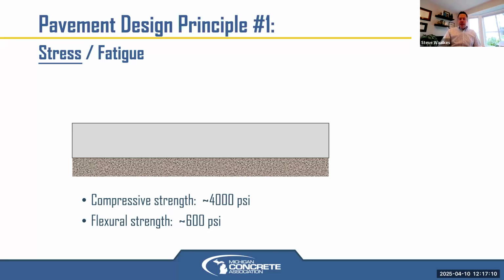As most engineers understand, we design things to reduce the stress on that member, on that material, whatever it is. And so that's one thing we can look at: what stress is being induced into this slab, in this case, slab on grade, fully supported. It's not a cantilevered beam or all these other design situations you may have learned if you had statics or dynamics or these other design courses.